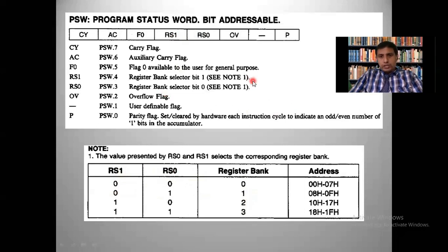So finally, what is your observation? In the 8051 microcontroller, we have some 8-bit registers and some 16-bit registers. For writing any program, we preferably need the accumulator register, the B register, and the R0 to R7 registers. In addition to that, we need the 16-bit DPTR register also. Like that, we can analyze the functioning of each register effectively.